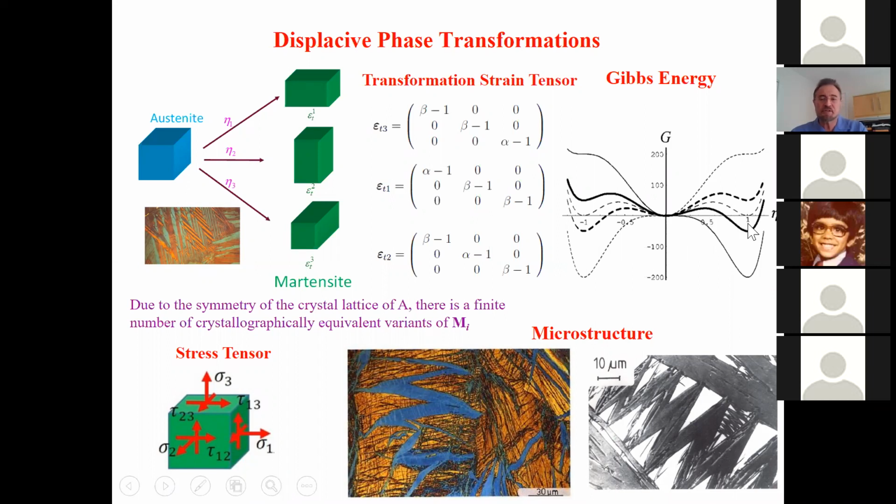So we need to further increase stresses and reduce the minimum until this barrier disappears. And when this barrier disappears, the low pressure phase loses its stability and transforms to the high pressure phase. And this is barrierless transformation. And we will discuss, this is the criterion for barrierless transformation. It's the same as the phase transformation criterion for ideal material.